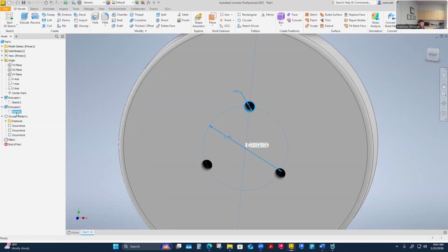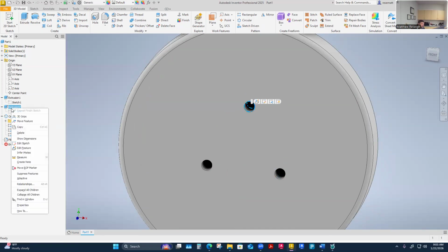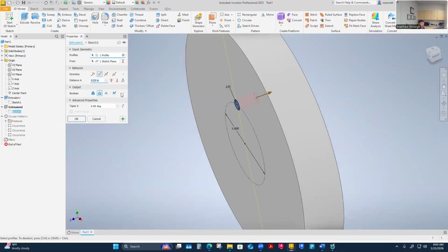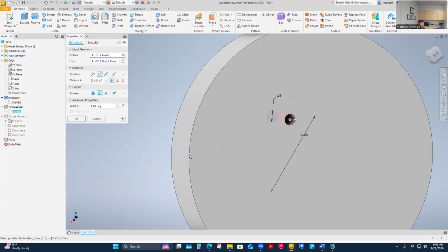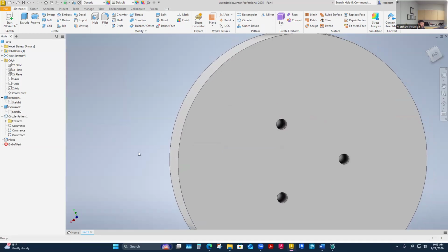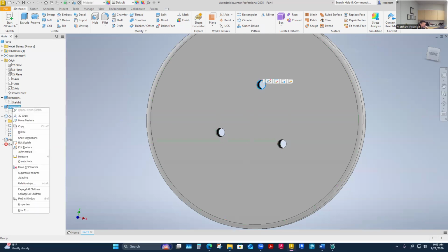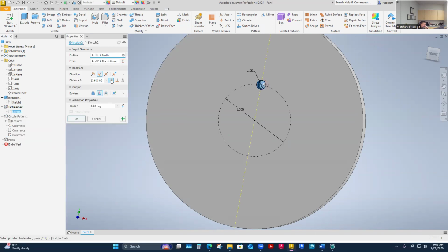And then I go into here, sketch two. Oh, sorry, extrusion two. I want to change now. And they would have you change this now to 0.5. I would change it to through all, and then it would solve the problem like that. Yep, that's me editing this feature here, edit feature. And then I click through all. You can enter 0.5 here because now your part is 0.5.